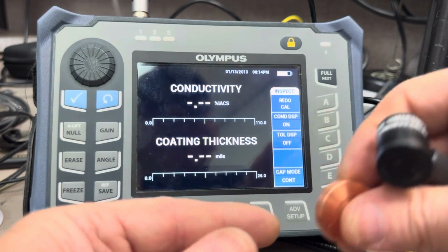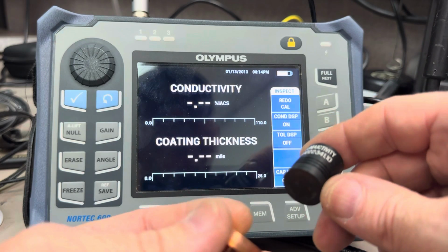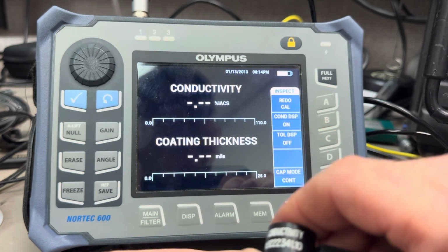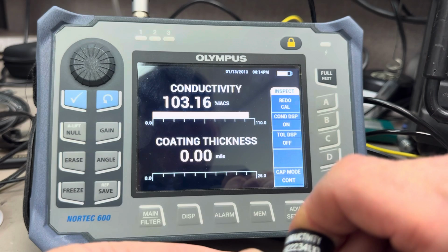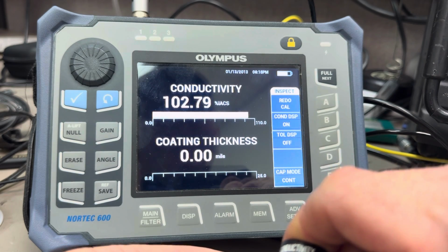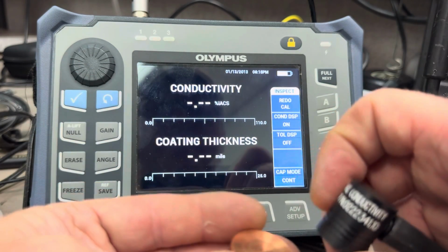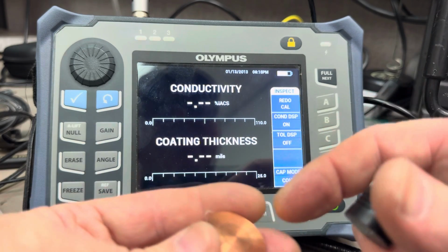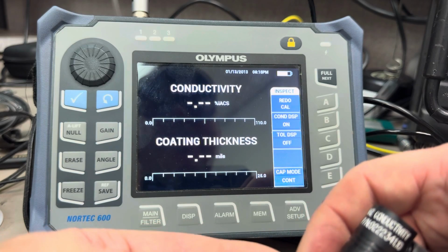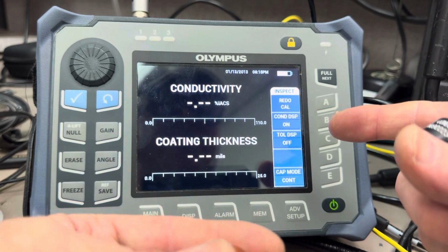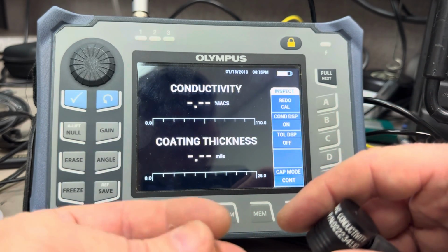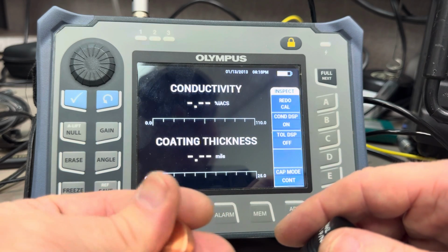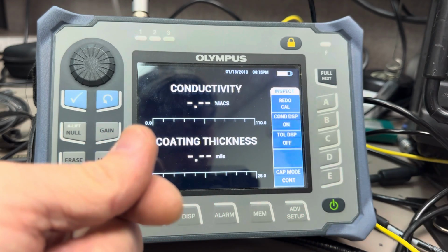Now what if we go back over to the 100? I bet you it's higher than 80 because we used the proper cal set points. Look at that. 103. So even though I went into this video with a certain intent, I noticed that I was off with my samples, and you can see how far off that can throw your test results. So your test results are only as good as your calibration. I hope you enjoyed the video.